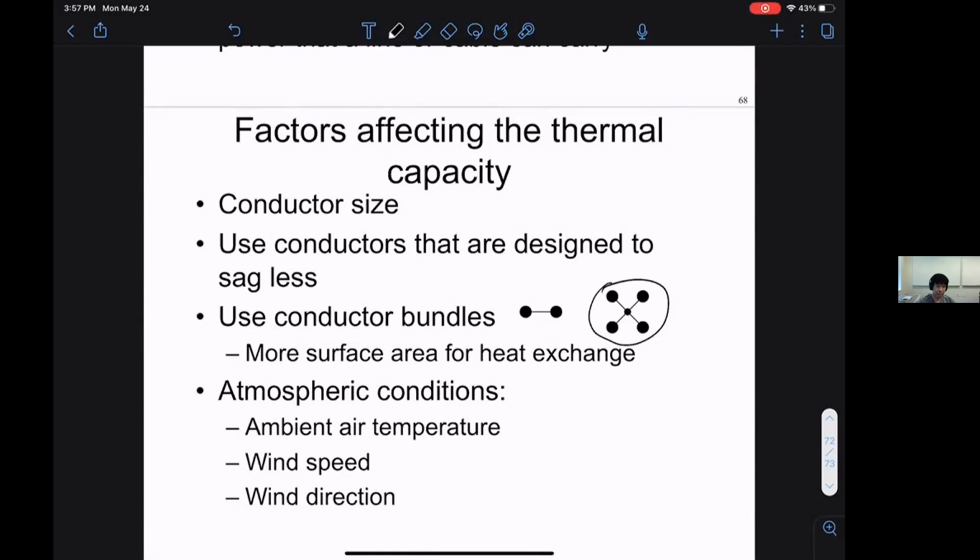So this is also another reason that limits the amount of power you can transfer. Power transfer is limited by either the heat you generate, or the synchronous reactance, or the maximum power transfer you have.